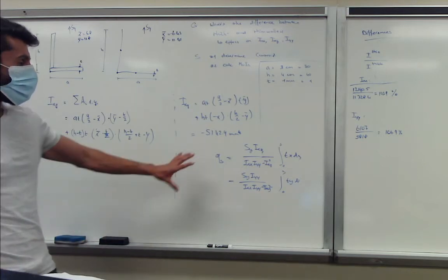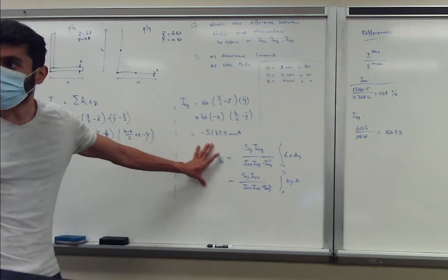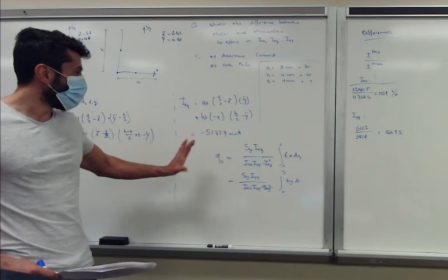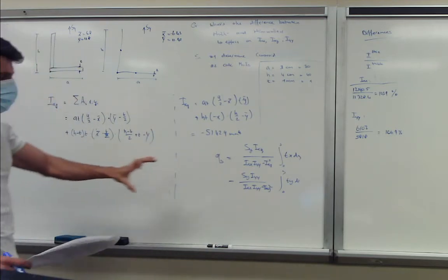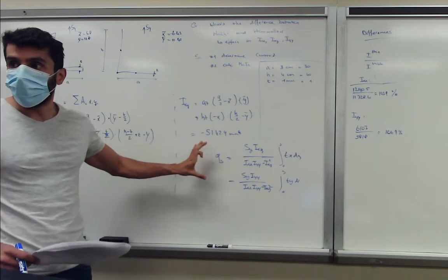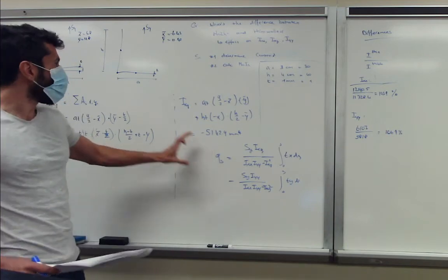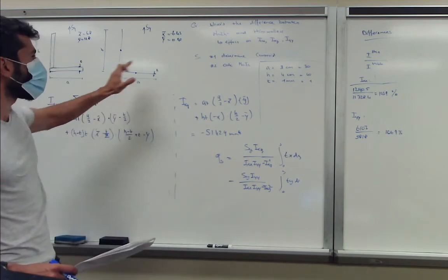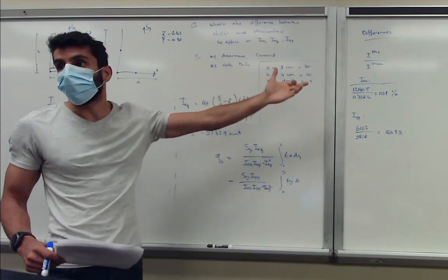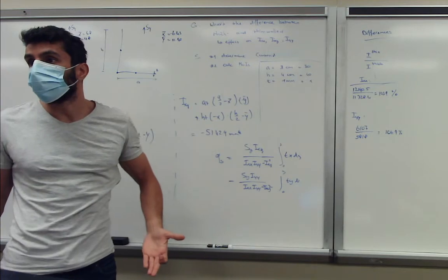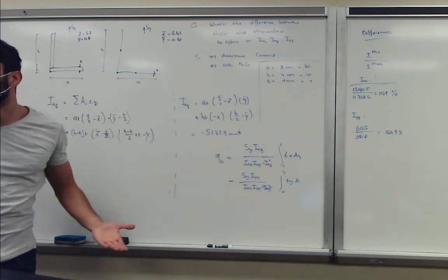The idea is to realize that this is basically a simplified version of the equation. So normally, what I would do if you get such a problem, actually start off with this equation, apply all the assumptions. Say, for example, if this was symmetric, then you could already argue that Ixy is not needed, and therefore make your life one step easier. Because Ixy will be 0 anyways.